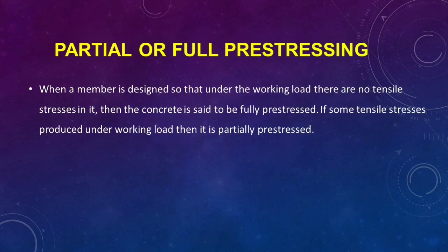Next is partial or full prestressing. If the prestressing is such that there are no tensile stresses in it under the working load, then that concrete is said to be fully prestressed. And if there is some tensile stress produced under the working load, then it is called partially prestressed.